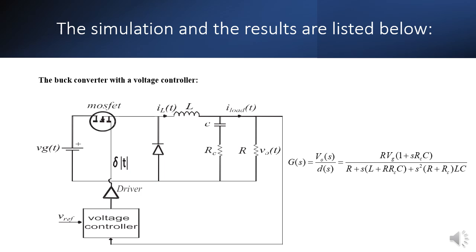The state space averaging method uses these state space descriptions as a place to start. By using this approach on the buck converter, a linear time invariant model with a state space description is produced. From this model, a number of transfer functions are eventually extracted, leading to the control to output transfer function that is maintained and shown on the right.